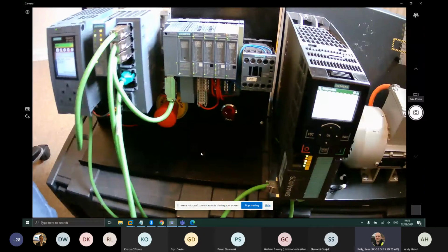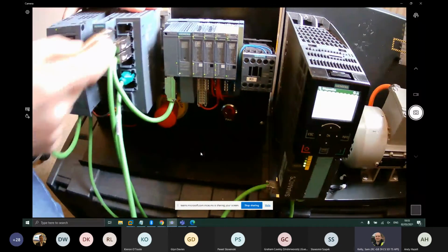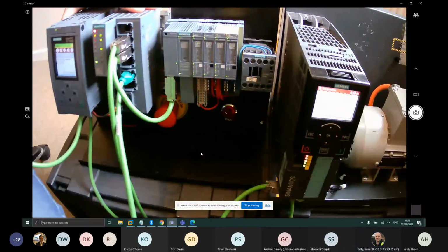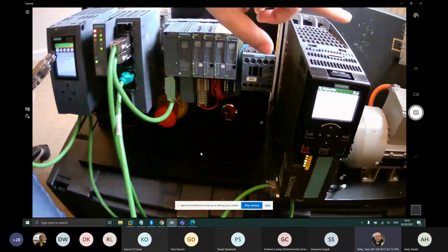And then what a customer might do is they go, well, okay, my MRP is set up. Let's test it. Let's disconnect something. So they'll go ahead and disconnect a cable. Oh, wait. Why is my drive tripped? That wasn't meant to happen. We also have some errors here. That's okay. The errors make sense because we've compromised our MRP network. Our MRP network is in error, but we didn't want the drive to trip.